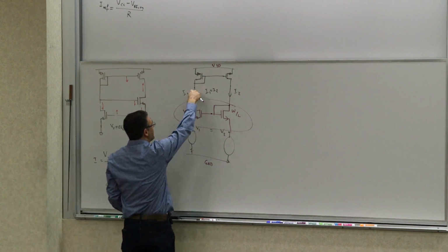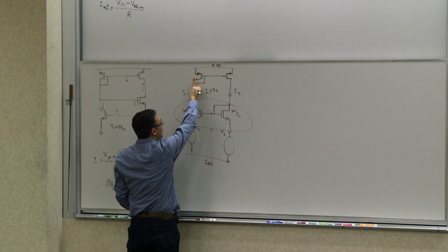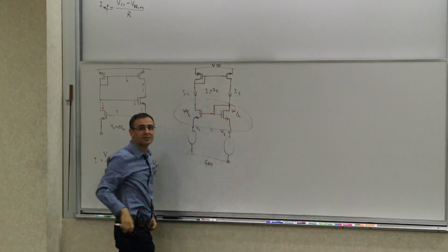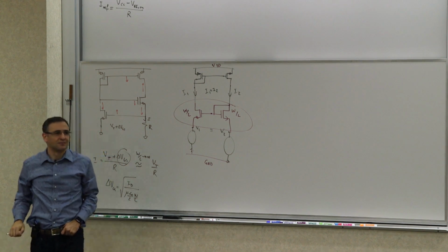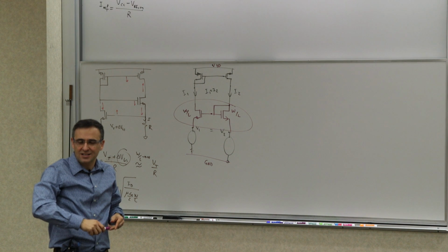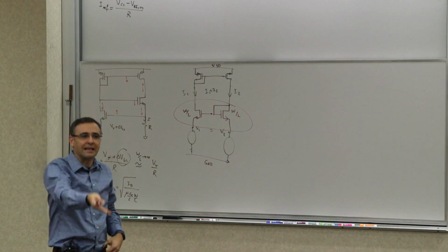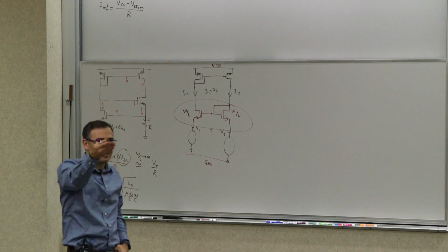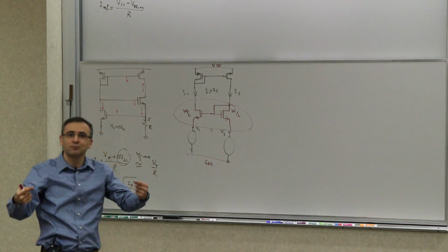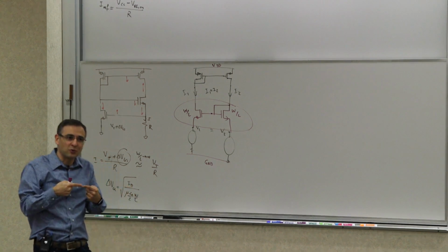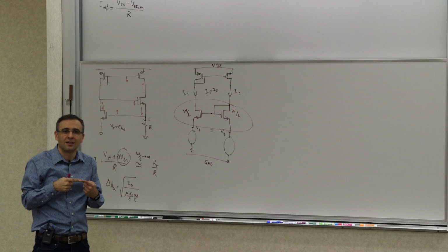Because you have a high impedance here and a low impedance up there, and a high impedance there and a low impedance there. So if you have one side that's high impedance, that side can play freely. It can be open. It can float. It can follow the other side. If you put 2 low impedances to one place, then you have 2 things that are fighting each other strongly.